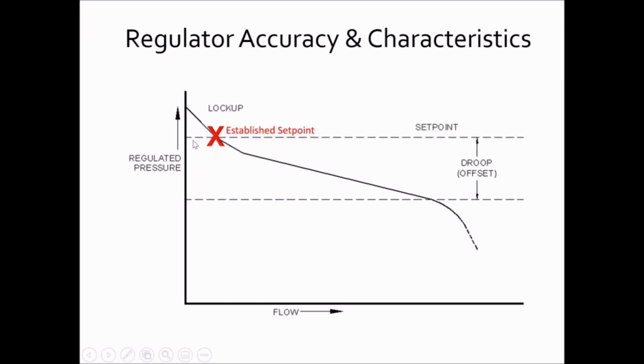So if we have this application set at 40 PSI, we start opening 10 GPM, 10 GPM, 10 GPM. Now we're only at 30 PSI, 35 PSI. So that is an inherent property that exists with pressure regulators. There is some pressure loss in the line if pressures are changing, or if flows are changing.